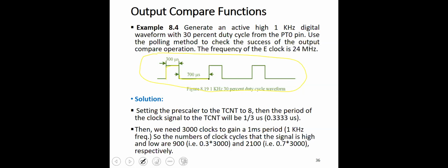But if we do it using software, we will keep the microcontroller busy executing the delay subroutine, which will consume substantial resources from the microcontroller. What is the alternative? The alternative is to use this dedicated hardware, which is the timer module, in order to free the CPU from doing this.